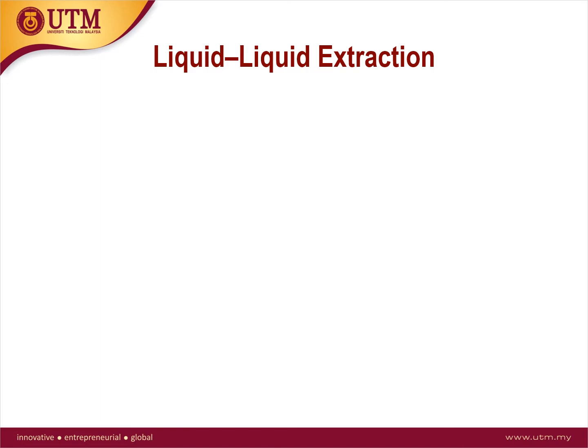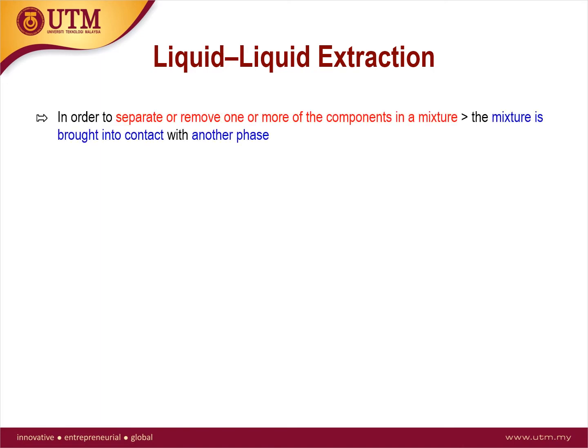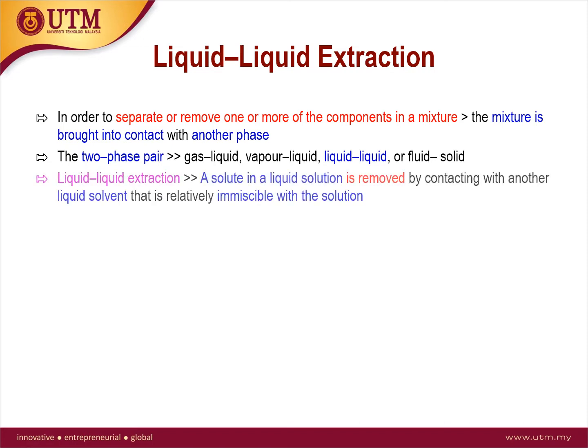Okay, now we move to the liquid-liquid extraction. In order to separate or remove one or more of the components, the mixture is brought into contact with another phase. The mixture can be in any two-phase pair, for example, between gas and liquid, vapor and liquid, liquid and liquid, and between fluid and solid. Firstly, we focus on the separation between liquid and liquid, also known as liquid-liquid extraction.